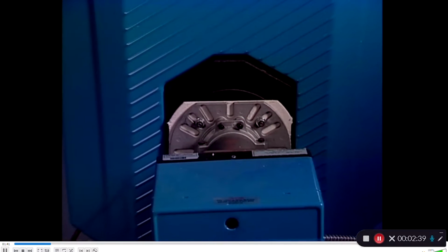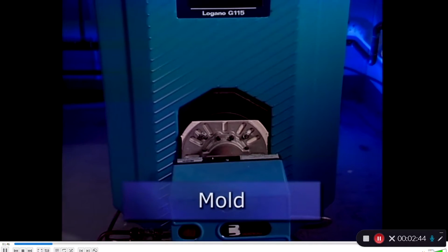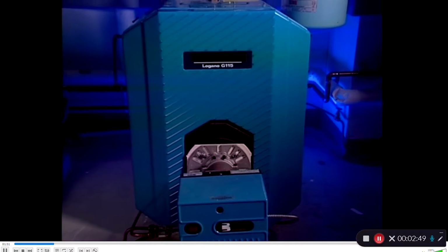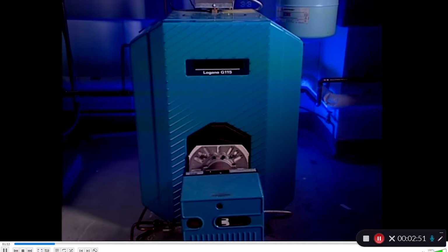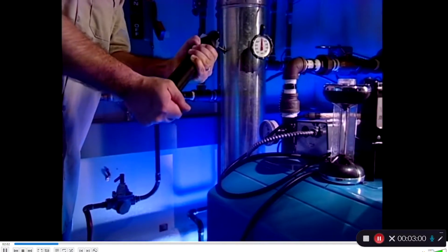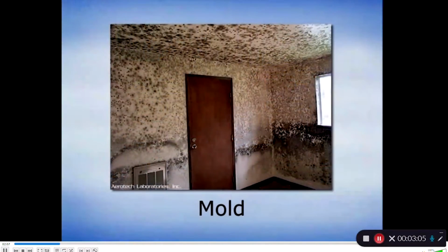Two other pollutants that have come to the forefront of concern are carbon monoxide and mold. Carbon monoxide is a toxic, colorless, odorless, and lighter than air gas. It is produced by incomplete combustion in fossil fuel burning appliances. Combustion tests should be performed whenever the system is serviced to be sure that carbon monoxide is not being produced. Mold can produce a variety of health problems in humans. The problems vary with the type of mold as well as the quantities.